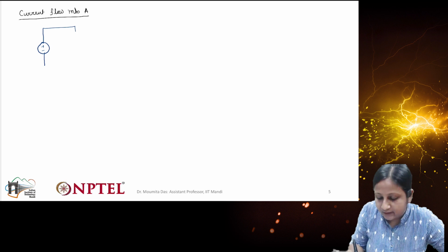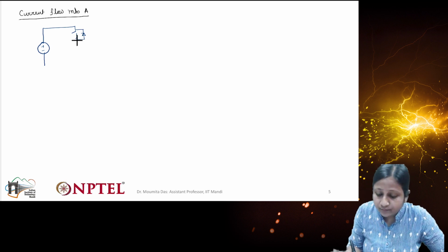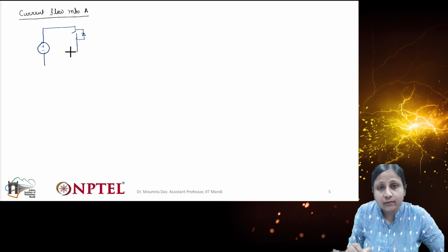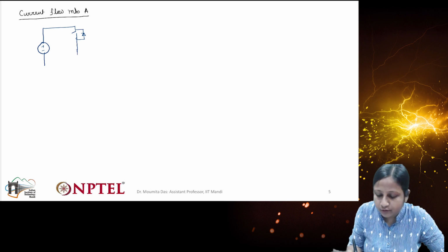Two switches are there, each having an anti-parallel diode. These diodes can be the body diode for wide bandgap devices, for example the body diode of silicon carbide. For GaN, it doesn't have a body diode but it provides a reverse path, so that will also work. There will be no problem for that.